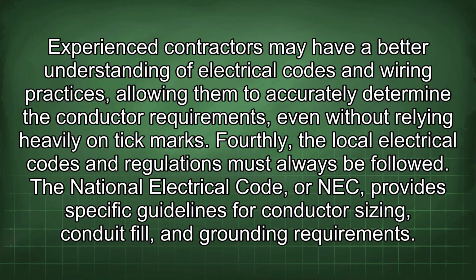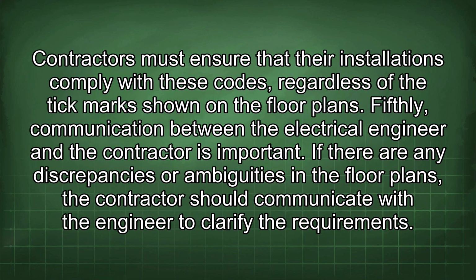Fourthly, the local electrical codes and regulations must always be followed. The National Electrical Code, or NEC, provides specific guidelines for conductor sizing, conduit fill, and grounding requirements. Contractors must ensure that their installations comply with these codes, regardless of the tick mark shown on the floor plans.